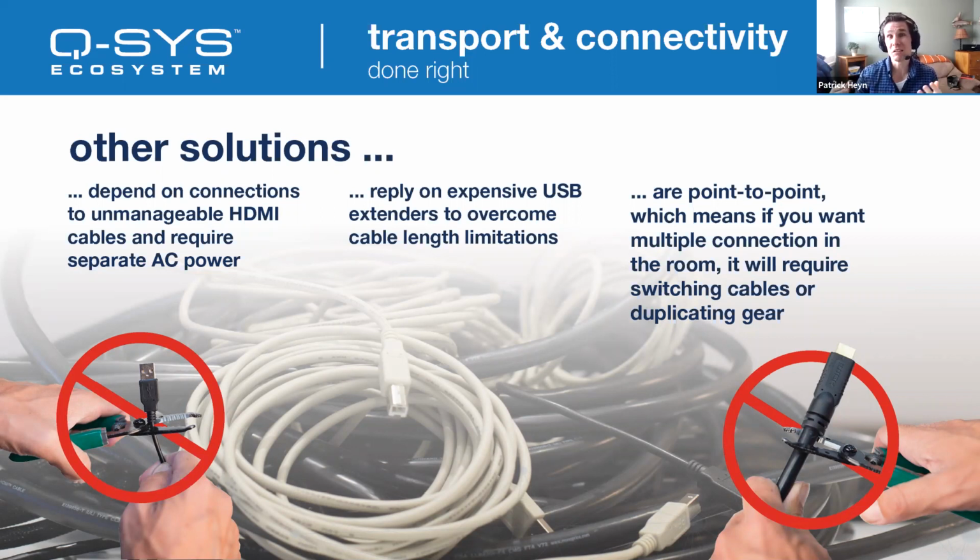And that's because, as we know, HDMI and USB, you can't field terminate them. They have length extensions. So it's really a problem of geography, because you're either dealing with those length extensions or you're trying to integrate these terrible workarounds like these HDMI matrices and USB extension cords that are both expensive and super duper unreliable.